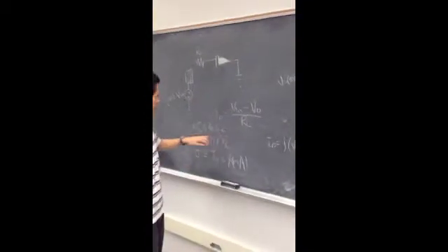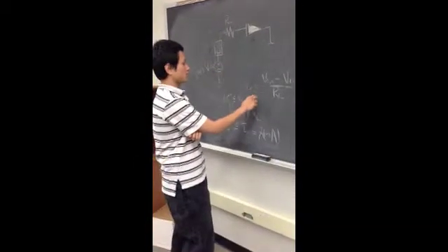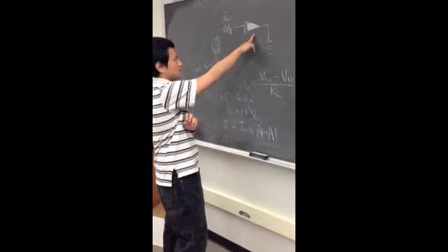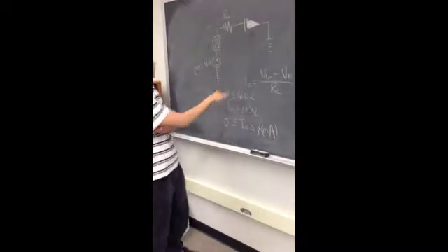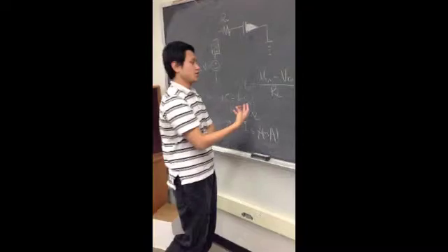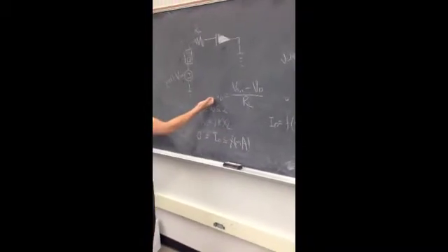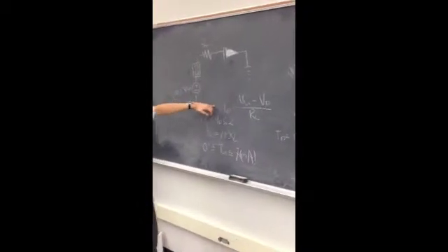Now, for a red LED, it takes 1.5 to 2 volts to actually actuate it. After it's actuated, the voltage across the LED stays constant, and then the current increases, and it varies the brightness of the LED. So therefore, this is the equation that will govern the brightness of the LED: the current across the LED, which will in turn govern its brightness.